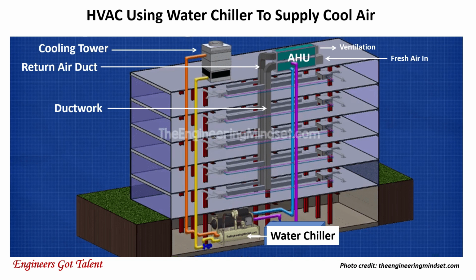Next is the cooling tower, which is normally located at the rooftop of the building. It cools down the warm water from the condenser. Next is the centrifugal pump, located close to the water chiller at the basement. The sixth is the boiler, to provide hot water to the heating coils. And of course, there's a pipe work to connect them all together.